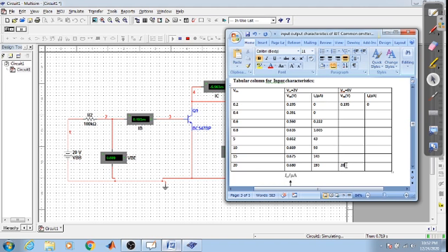You do it with Vc equals 2 volts and Vc equals 3 volts. So you set the voltage here and you vary this Vb. After whatever the Vbb voltage may be, after 0.699, the current starts rising in this fashion. That is what is being shown here. It is increasing almost exponentially. It started from 0, 0.22, 1 point, next it is 43, next 93, 143, 193.